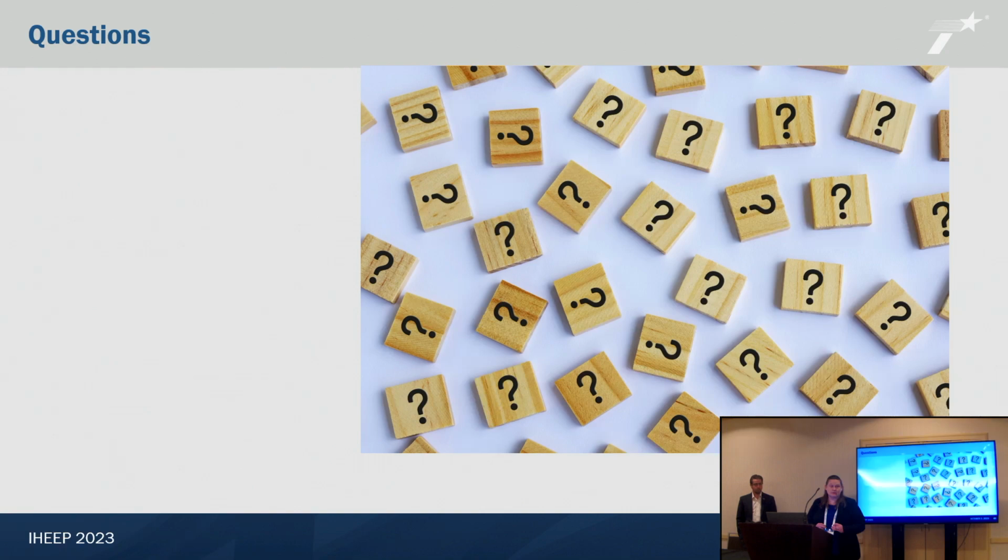Especially with widenings, but then again, the widening that we showed, there was an existing abutment out there, and they surveyed it 3 or 4 times and got a different bearing on the abutment each time. So any survey is going to be a little bit off. But for me, it's helpful to know where it is, to know if I've got the vertical clearance or horizontal clearance. And that doesn't necessarily have to be 1/4 of an inch. Anything there would be helpful. And as far as building, I'm sure your templates are according to the new standards, but they might not fit with the survey. Obviously, the as-builts are going to be slightly different in all of those particulars.